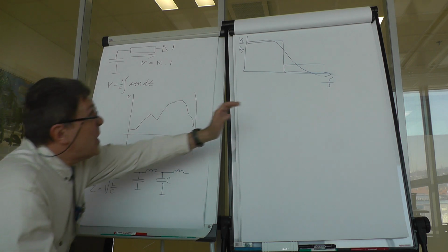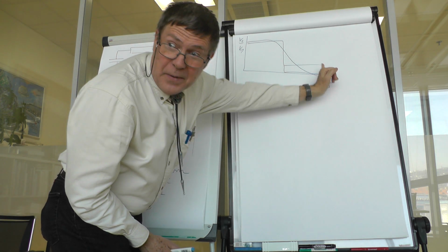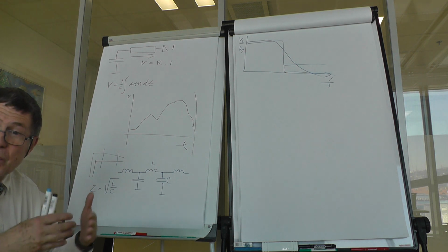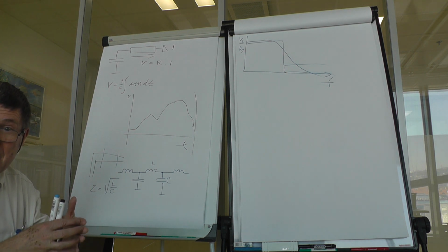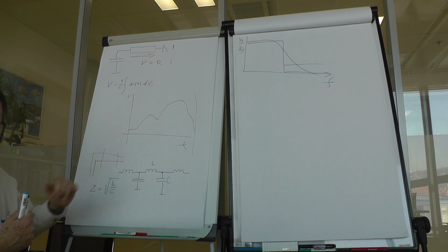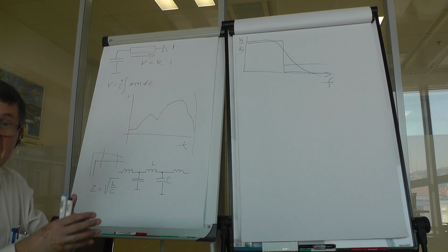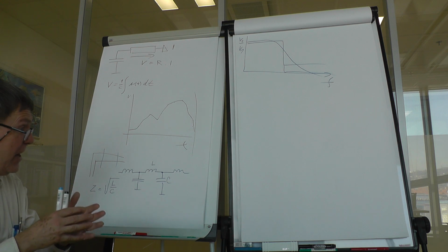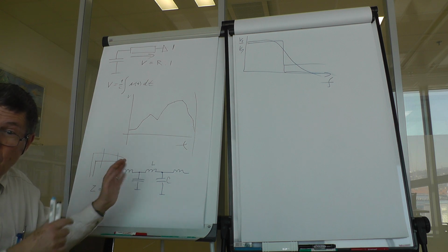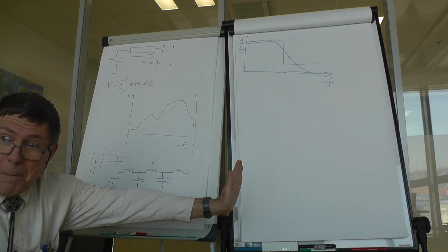But you would shift the frequency to a higher one. So this is easy. You can still have a model comprising inductors and capacitors which mimics the transmission line. Just you have to take care to get the cutoff frequency of the low-pass circuit sufficiently high.